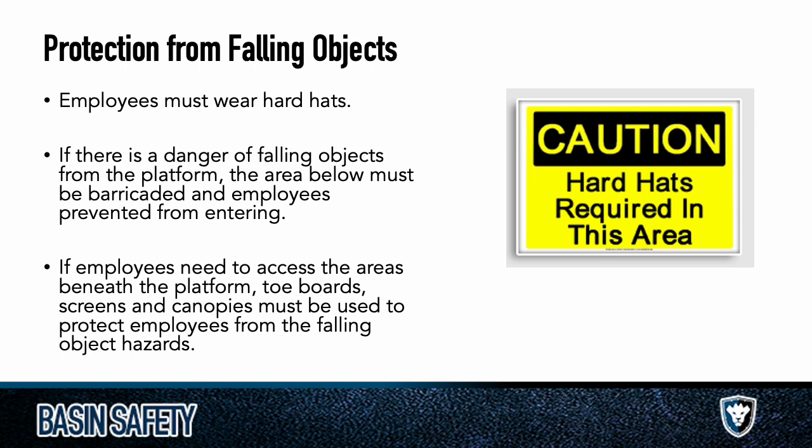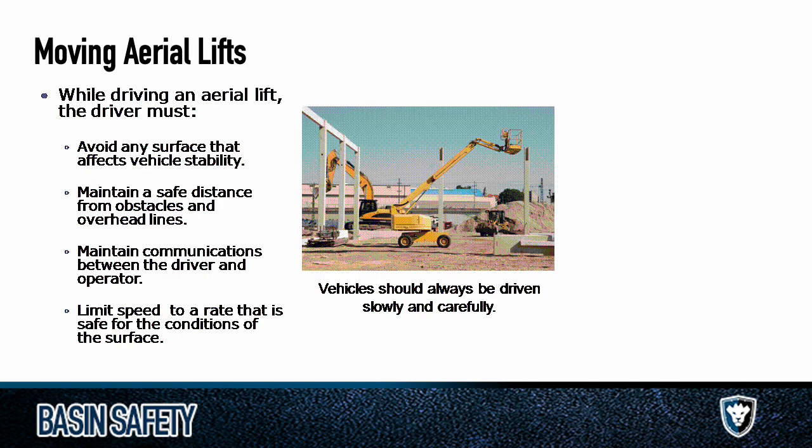It's not a bad practice to wrap your cords and have tie-offs and anchorage and things like that. But screwdrivers. A screwdriver falling from 50 feet is a missile, and it can mess you up. So just keep that in mind. Don't let people walk underneath you because you're a suspended load, essentially, when you're up there.